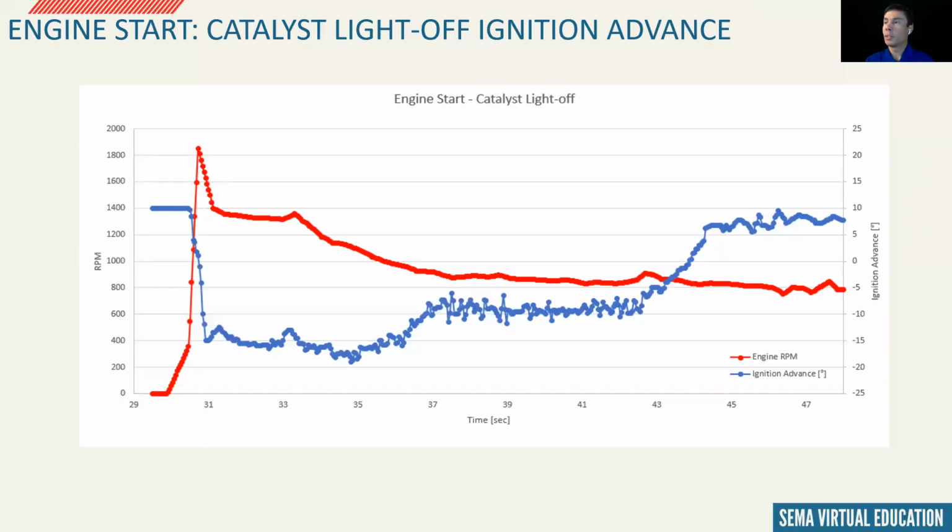Now we're going to focus on the engine start. During a cold engine start, tailpipe emissions will equal the engine out emissions, because the after treatment or catalyst is not active. Because of this, a majority of emissions will accrue during the first phase of the FTP. During phase 1 of the FTP, the ECT, IAT, oil temp, and catalyst temp will be around 20 to 30 C. This is the test lab requirement for ambient temperature. This is also after a specified soak to normalize temperature.